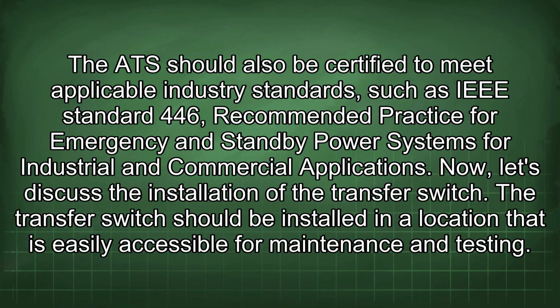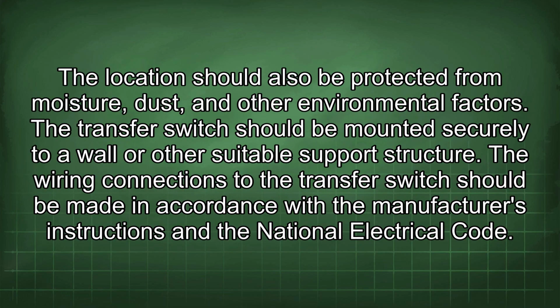Now let's discuss the installation of the transfer switch. The transfer switch should be installed in a location that is easily accessible for maintenance and testing. The location should also be protected from moisture, dust, and other environmental factors. The transfer switch should be mounted securely to a wall or other suitable support structure.